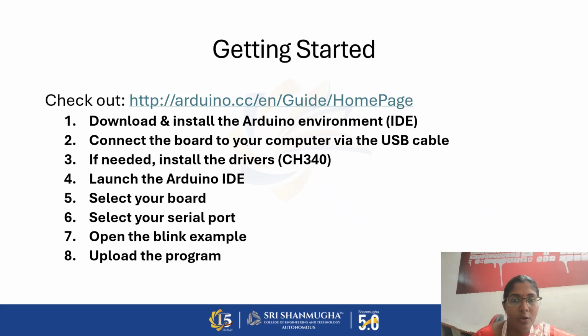You can download and install the Arduino IDE software by using this link, and I will provide this link in the description also. You can also Google it as Arduino IDE. It will lead to this link, and you can download and install the Arduino IDE. After installing it, you have to connect your board to your computer via USB cable, and if needed, you have to install the CH340 driver.